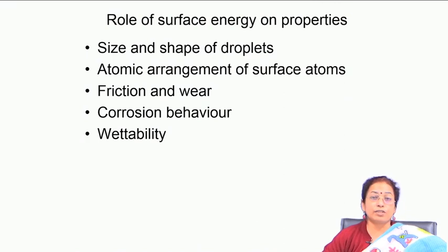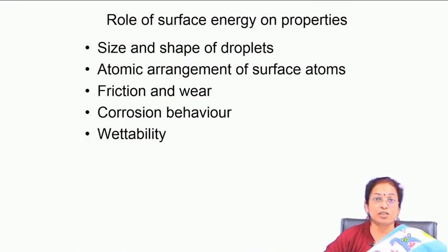Now, if you talk about the role or importance of surface energy, it influences many important phenomena, for example the size and shape of droplets, the atomic arrangement of surface atoms, friction and wear behavior, corrosion behavior, and wettability. All of these depend on the surface energy, and the driving force is the free energy change associated with lowering of surface energy. When you create a surface there is an increase in energy, so naturally the driving force is the lowering of that energy.